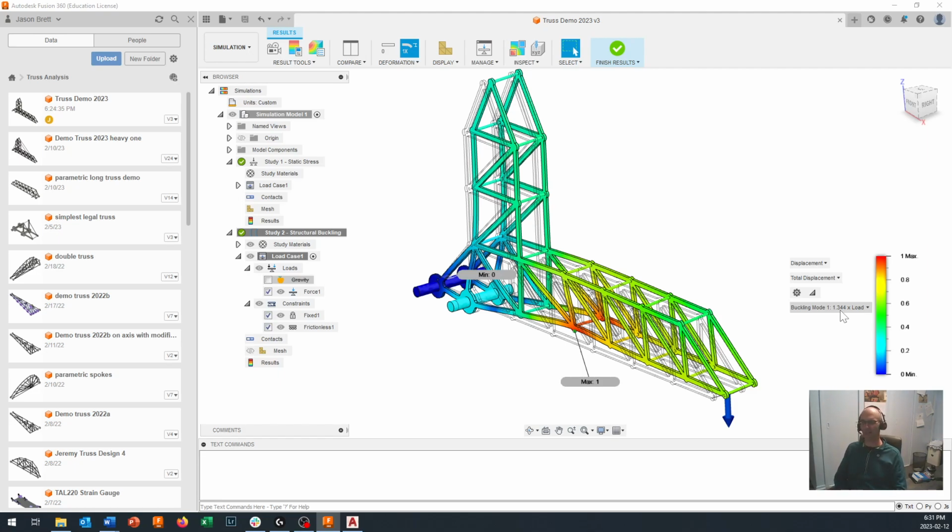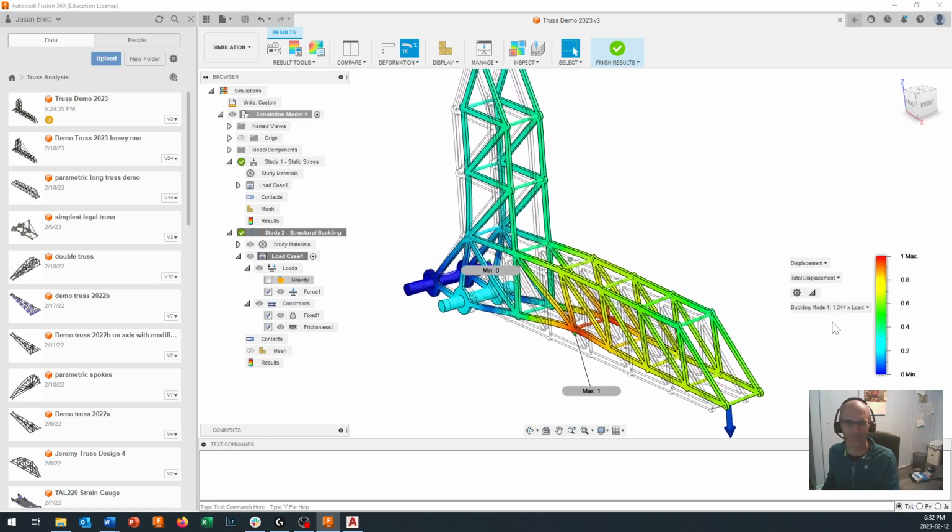I think the value that I put in for Young's modulus, 3.7 gigapascals, was a bit high. But if you want a more accurate value, you're going to have to go and spend some time in the shop and do a couple little beam bending calculations to try and get a more accurate value. All I know, 3.7 might be a bit high. No, I'm not going to tell you what my calculations were, but I will show you how to do them.